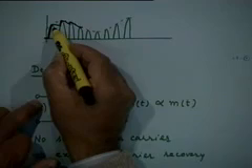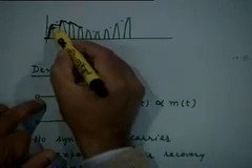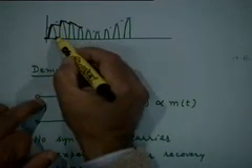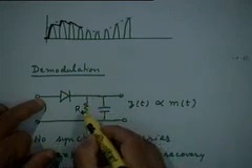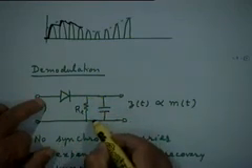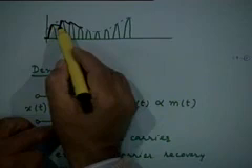And when the input voltage now drops, this diode becomes reverse biased, because this point is at a higher voltage than this point. So there is no conduction; the diode remains reverse biased during this falling portion of the carrier half cycle, and during this period the capacitor discharges through this load resistance R sub L, and let us say there is a certain discharging time constant which is not too fast. We don't want the discharging to be too fast, so that it more or less stays at the constant value that it had charged to, right, except that it decays just a little bit, right? And then the next half cycle comes in.